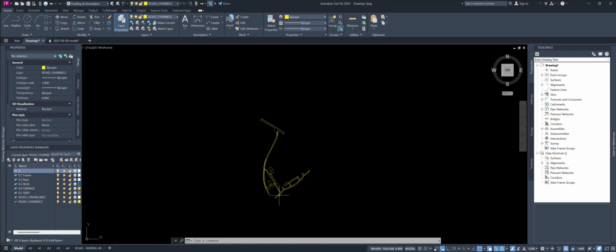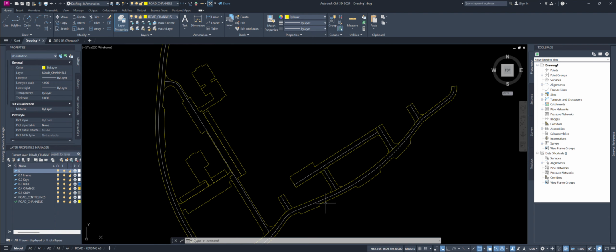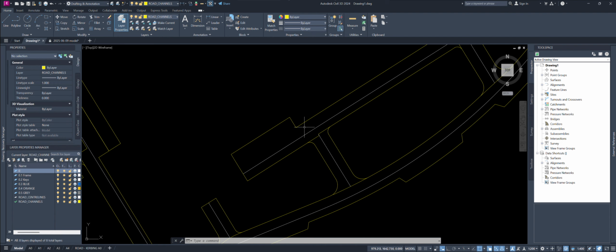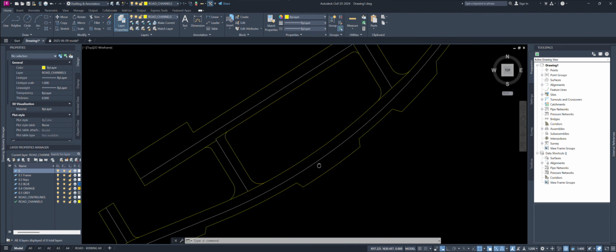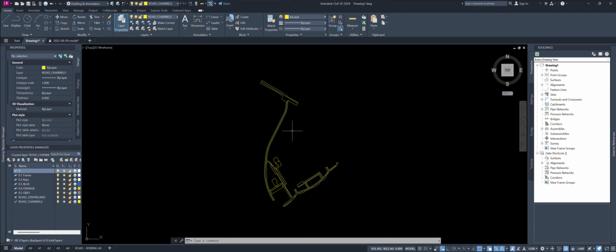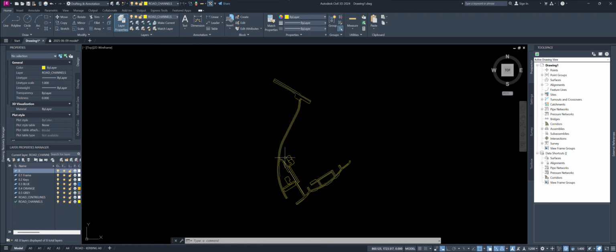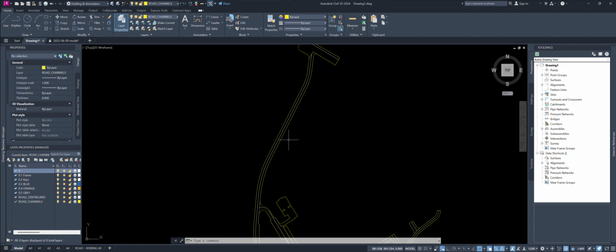So again, you can see how many places we possibly can forget that we're still snapped on that line. With this, we avoid extra errors. It happened to me personally many times, realizing I'm still snapped somewhere back here and I'm giving a level based on that bit, so I have to literally go back and reset the height of my profile because I didn't pay attention.